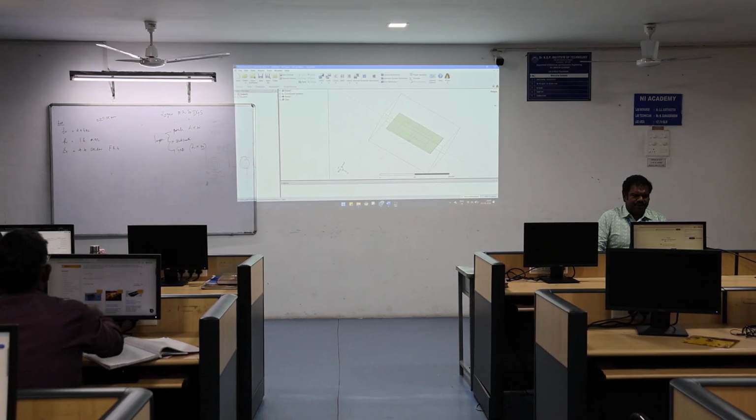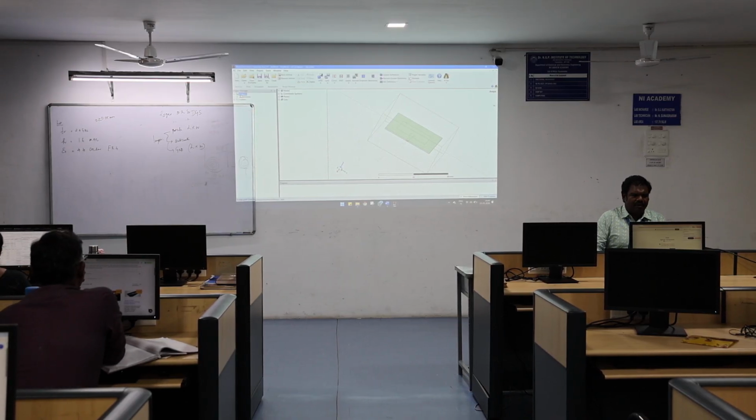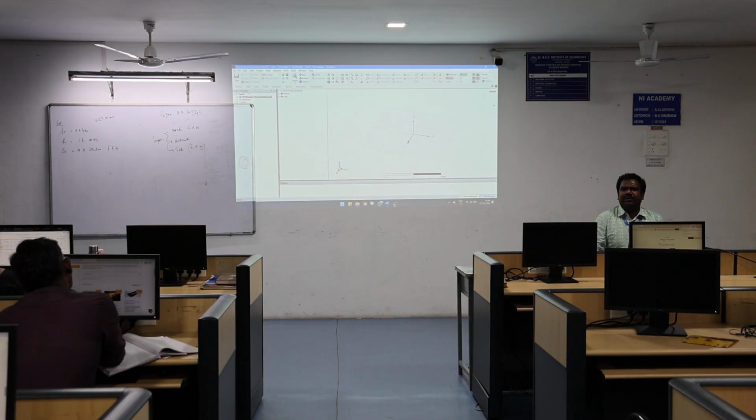First, I choose a new model. The new model you have to rename as test 1. So I rename it as test 1. Double click on this model. Insert one new HFSS design. Insert the HFSS design. One new design is there.